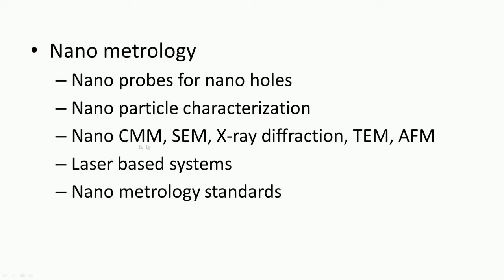Then in the last few decades, various measurement methods have been developed for the characterization of nanomaterials, like nano CMM, which physically measures the MEMS products and nano products, and then scanning electron microscopy, X-ray diffraction, tunneling electron microscopy, atomic force microscopy, all these are developed which aid the characterization of nanoparticles, nano devices, etc. And then recently laser based systems are developed which aid in inspection of nano devices, and there is a need to establish nanometrology standards so that in all parts of the world the same standards can be used, and the measurements carried out in nanometrology will be comparable and usable throughout the world.